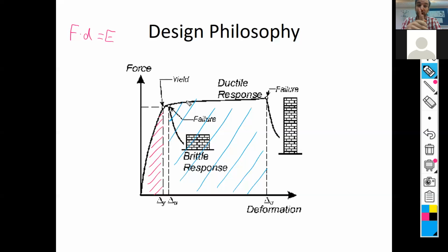While if the structure is very, very strong, very, very stiff, it means that whatever you do, it will not be plastic, and every single little impulse coming from the earthquake will result in increased vibrational energy. So even though your structure is very strong and very stiff, you can accumulate enough energy so that you shake it until it collapses.